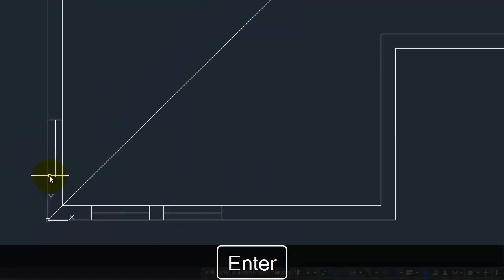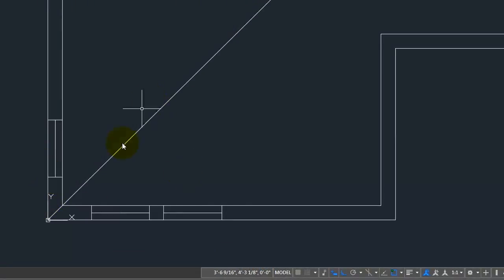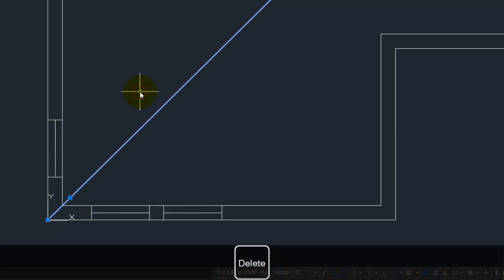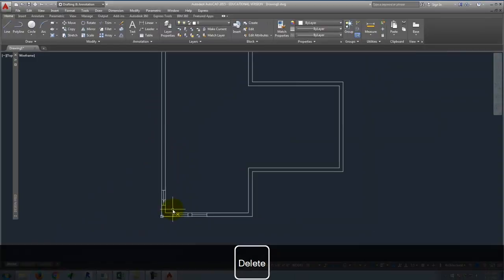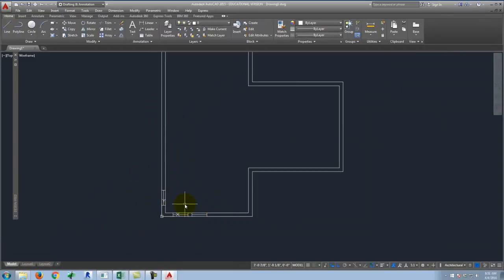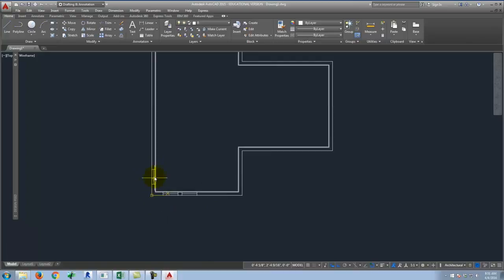So instead of mirroring straight from one to the other, I mirrored across those corners to create this window. So in terms of number of clicks or number of steps, that is much, much shorter. Just click on one corner and then the other corner. Since they're 6 inches in both directions, you know that it's 45, like that. So that gets you a window off of that line.